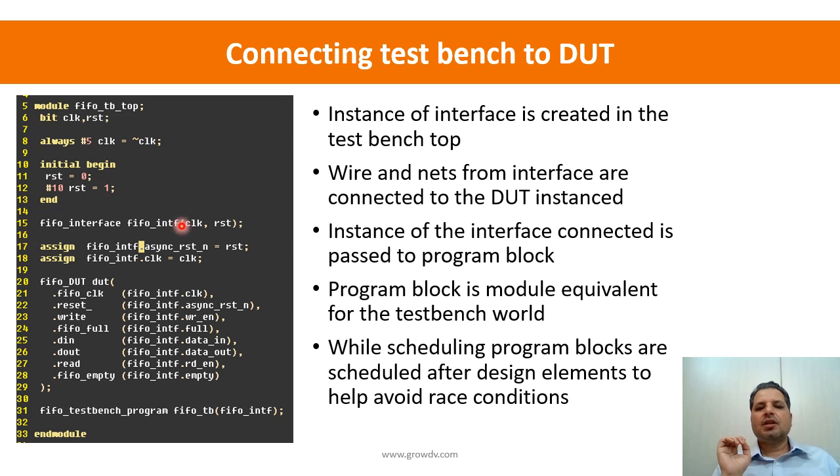Now the important point over here is that we are creating another instance. This is the test bench top instance. Typically in the SystemVerilog world, we use another construct called a program block. A program block is again a module equivalent.